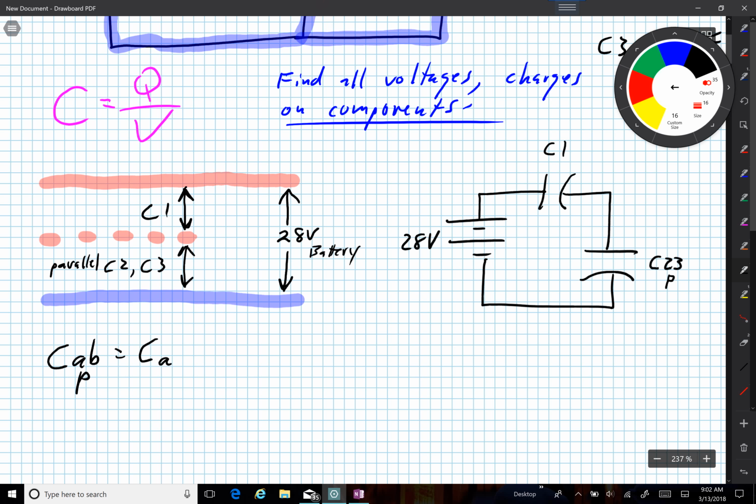So I'm continuing to look back and forth at the schematic diagram and then looking over here at my color ladder to see if I know a voltage that I would need to apply my governing equation. And I'm not finding it, so I have to keep doing equivalent circuits.